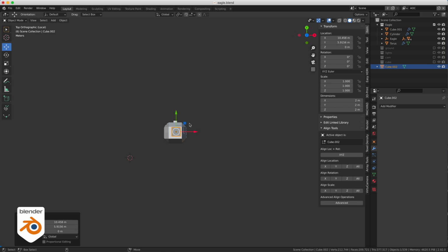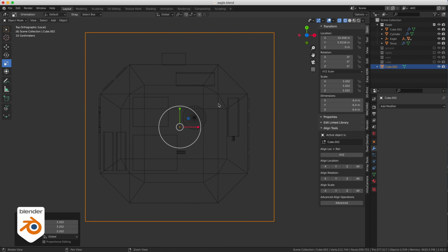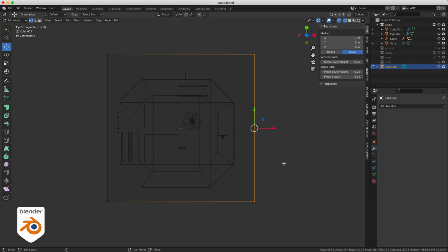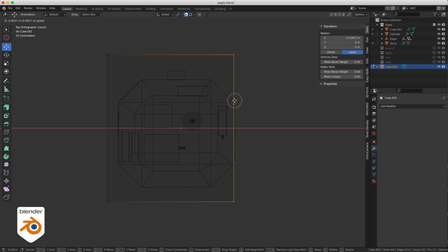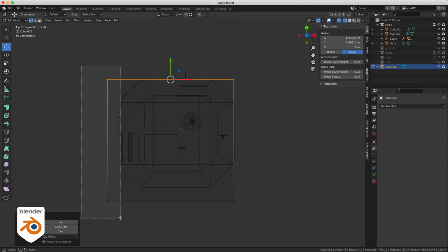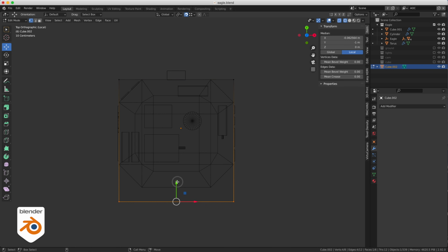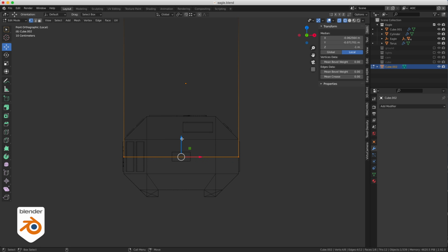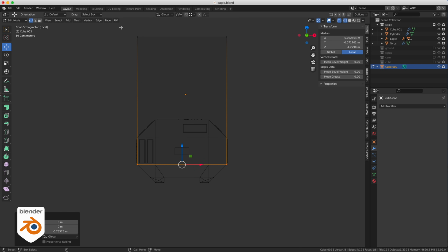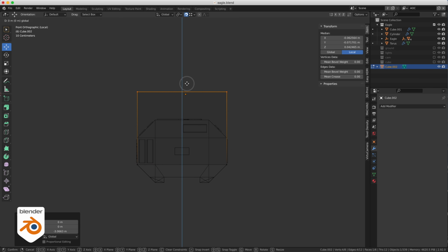Well, this is a cube. Yeah, we're going to start with a cube for this one. So cube, and we're going to center it like we did before. Now what I'm going to do is go into wire mode, and I'm just going to move the points and snap them on the edges like we did previously, with the snap turned on here for the vertices, and I just move it to snap like this on the edges of the geometry.